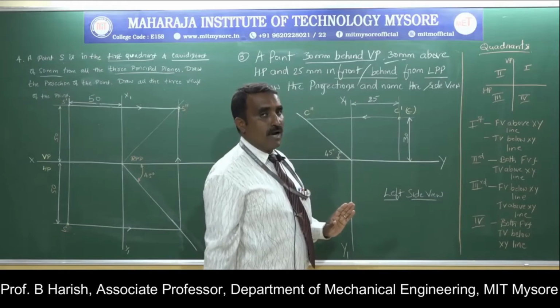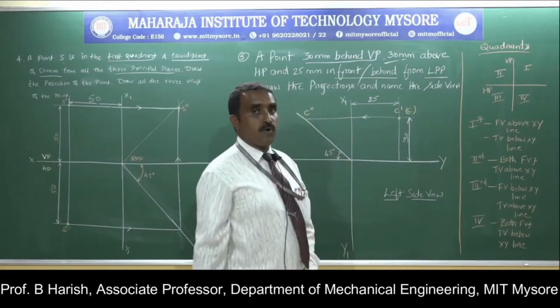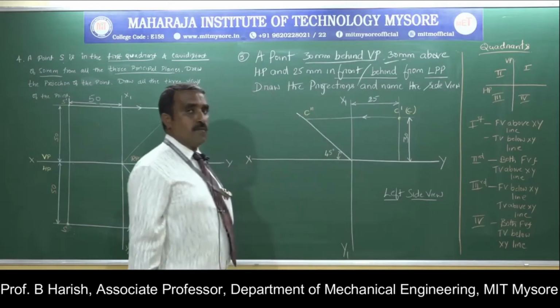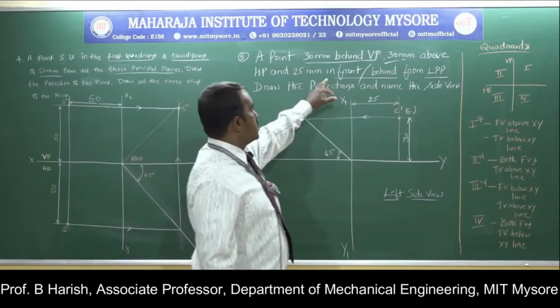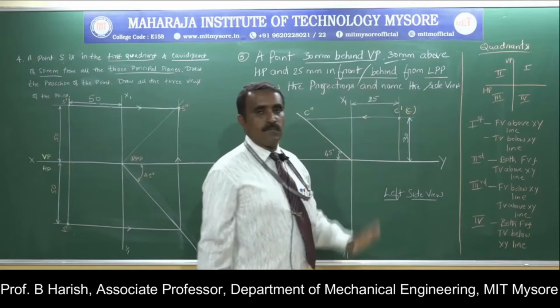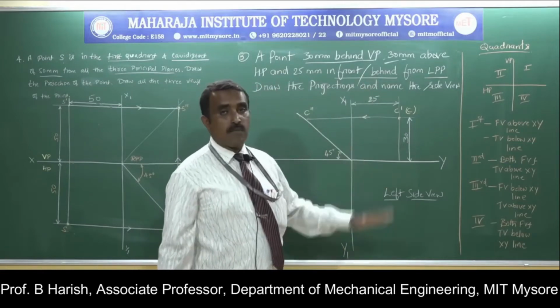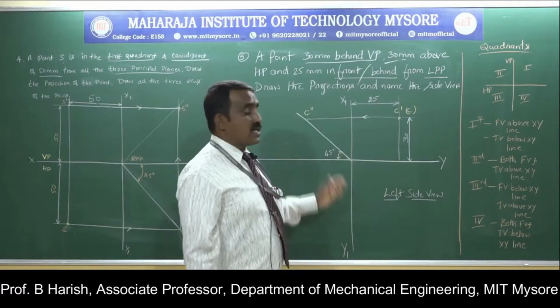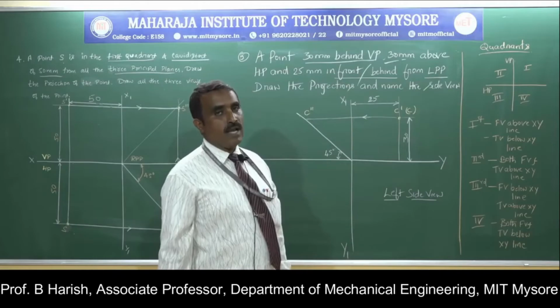Now I have to draw the profile view. For drawing the profile view, I should fix the profile plane. So where do I have to fix the profile plane? Go to the problem. It says 25 mm in front slash behind from LPP. LPP means left profile plane. So I have to fix the left profile plane and then draw the profile view.